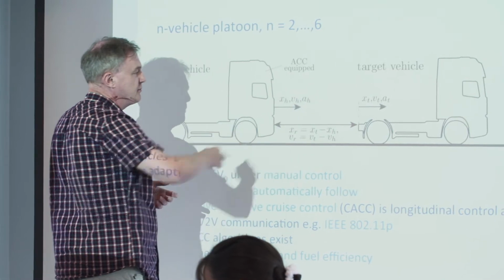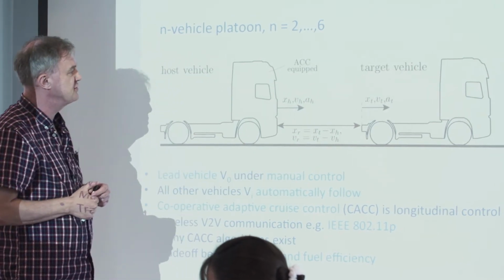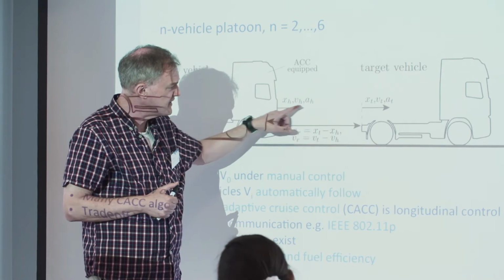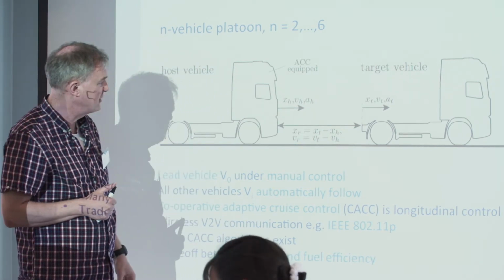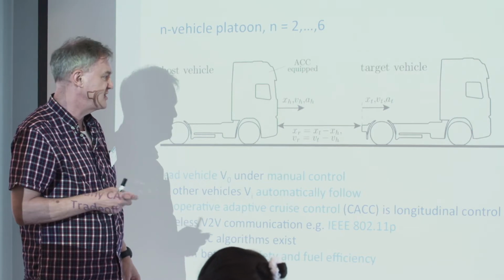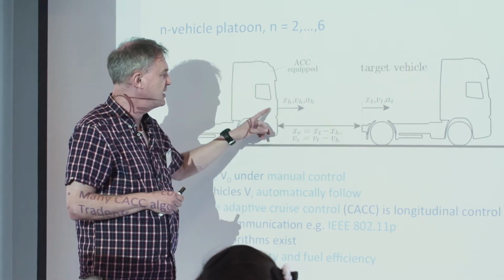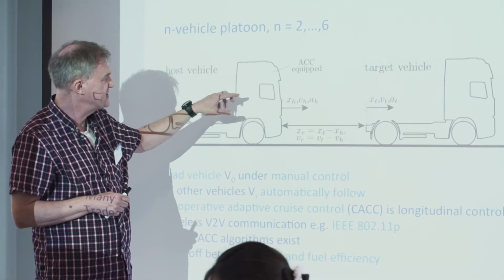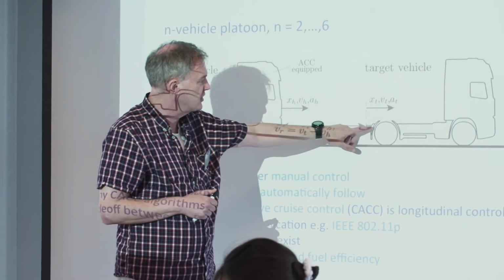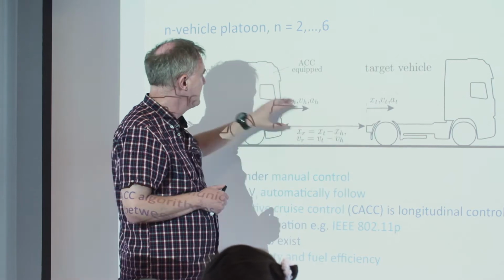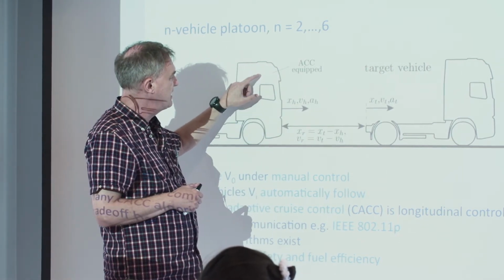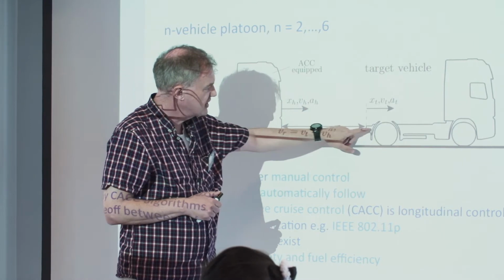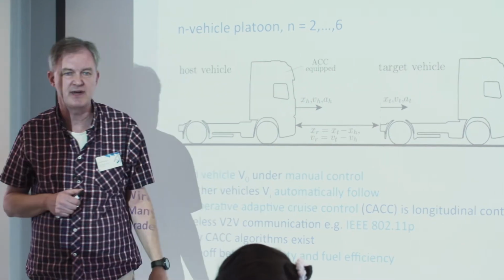There are at least two different protocols for platoons. One is fixed distance, which I think is commercially the one that one sees more commonly. For other internal reasons, we looked at fixed time headway. So the time headway is, if you freeze this picture at any time, you look at the velocity of this vehicle here, how much time would it take for this vehicle at its current velocity to catch up to that position? Okay, that's the time headway.